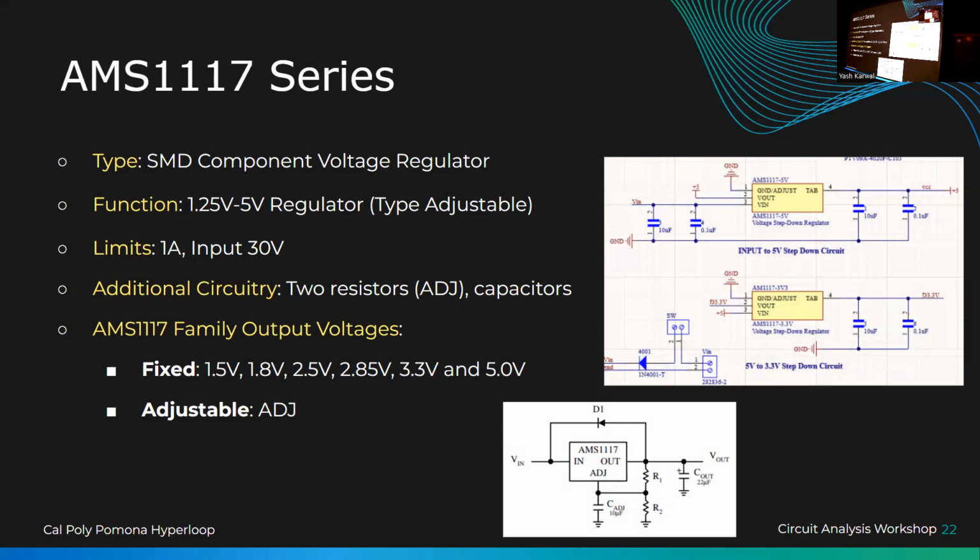That chip is basically a voltage regulator, but now it's the flat one. Earlier you saw the big chunky one, right? The one that you have to stick in and solder through the hole. This one is surface mounted. Same deal with all the voltage regulators. You put it in, and this is also the adjustable one, so you change the resistor values and you'll be able to output a voltage that's not higher than the input